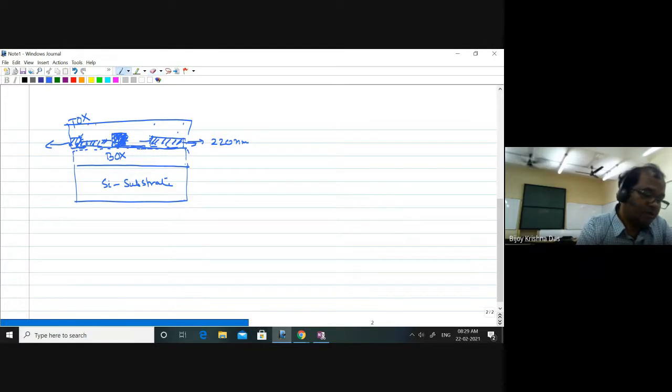Yeah. So this is your silicon layer you are leaving. This is your silicon layer, and this region may be your top oxide layer or ER, whatever. Then this can be considered as a core waveguide, and this is called rib or ridge waveguide structure. And whenever you are removing completely, then it is just rectangular cross section. It can be rectangular, it can be square or whatever, depending on your design.